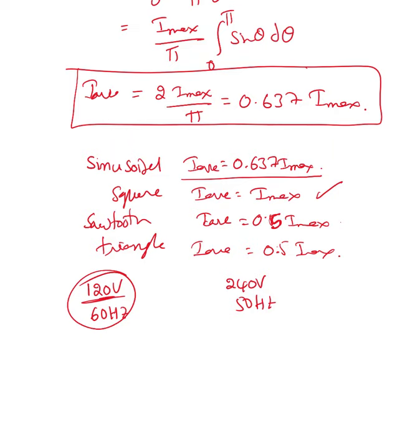So in the future, wherever you see a voltage in AC, whatever voltage we are talking about, we always give them in RMS values. If I say 120 volts is coming out of that outlet, or 240 volts is coming out of that power outlet, then that value is the RMS value all the time, because that's the equivalent of energy transfer with a DC circuit.